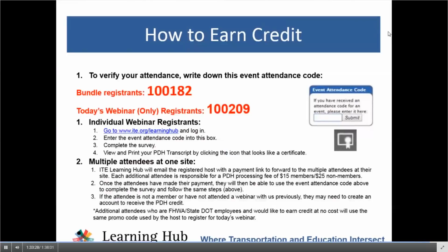and I really would like to again emphasize that level of service I know is a very convenient number, and I know the HCM has a lot of legacy of providing it, but really the HCM as well as other analysis tools provide a whole host of performance measures. And so I would encourage, as states are looking at ICE policies, to really look beyond just that one letter grade, which even though it's convenient and may be needed for efforts like a statewide prioritization where you compare hundreds and thousands of projects, for a project level assessment and determination, really there are other metrics that much better express and quantify the operations of an intersection versus another one.